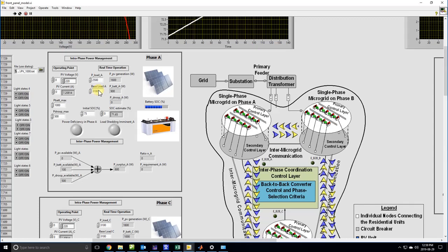Okay, so what we are seeing over here is that with 2500 watts of load power, the PV generation is about 1600 watts, and this 1600 watts needs to be contributed to the P load. Secondly, 900 watts of battery power is required to support this load, because all of the maximum PV power is being contributed to the load, so the battery has to come into play.